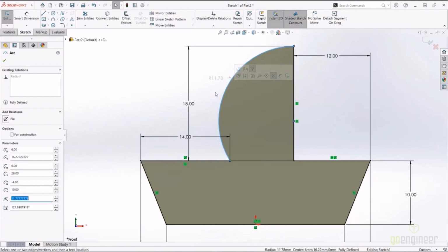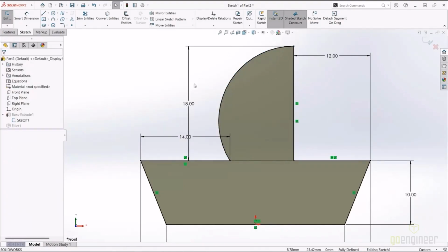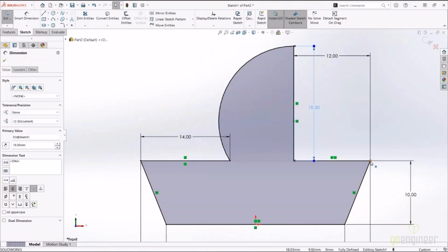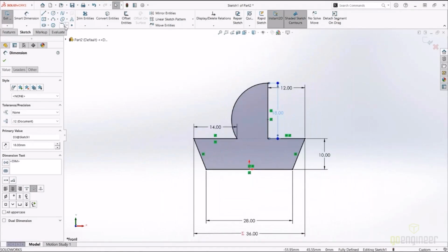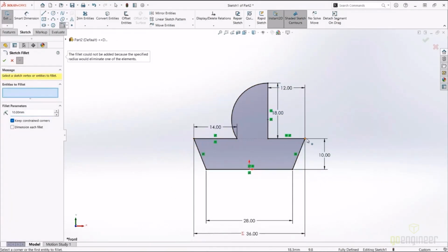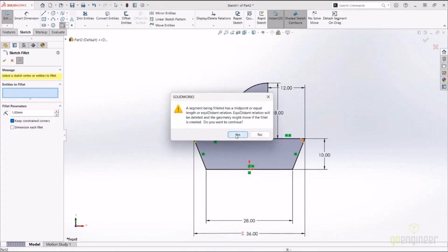Now, this arc I clearly needed. The front of this sail, I needed that arc. I had to put that in the sketch. But if I'm dimensioning to all the sharp corners, then I don't need those arcs in the sketch. Now, if I do want to dimension the overall length with the fillet, then I would need the arcs inside of the sketch.